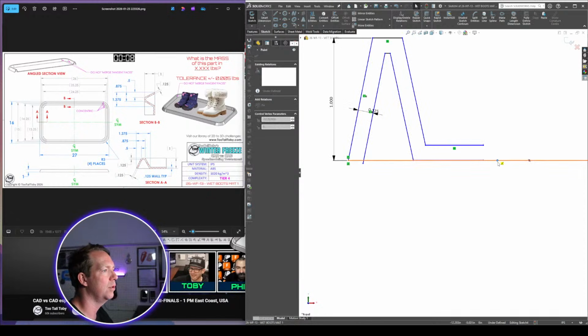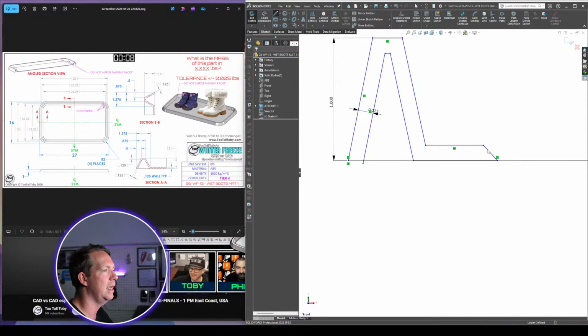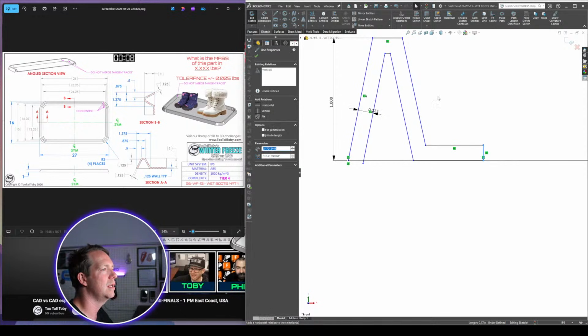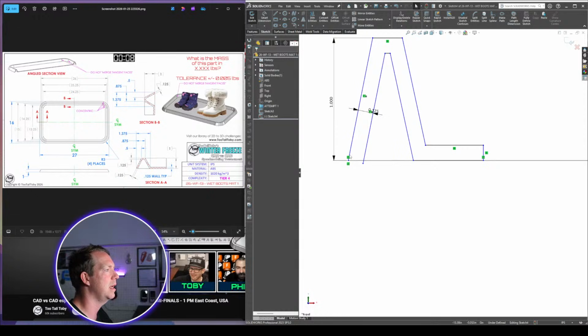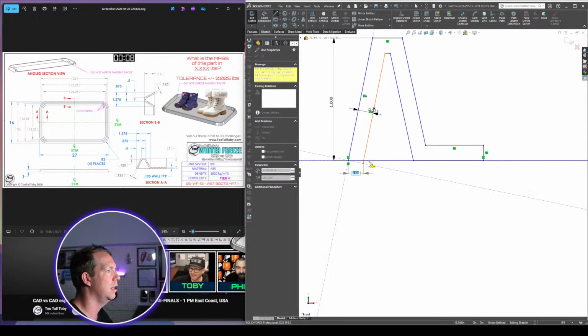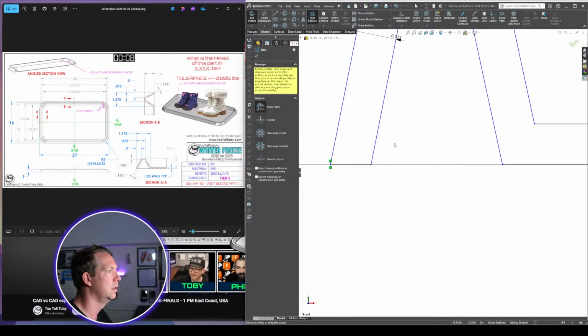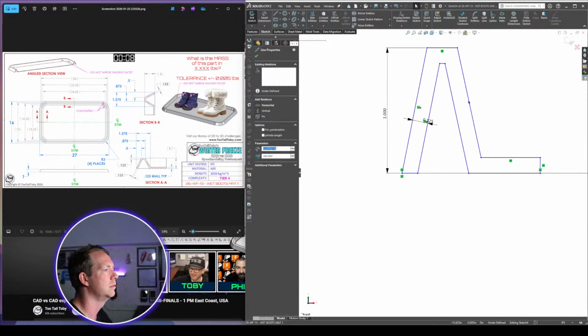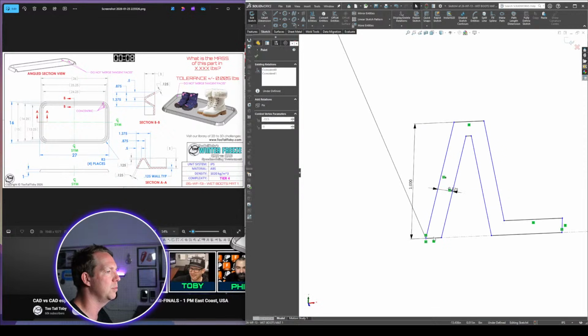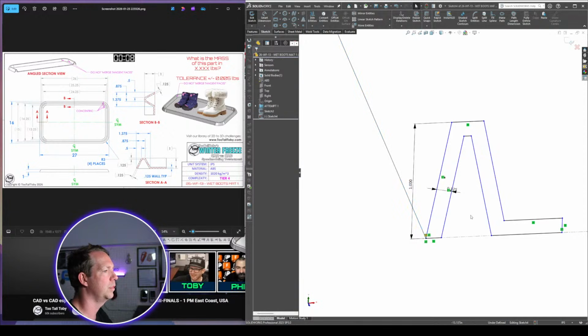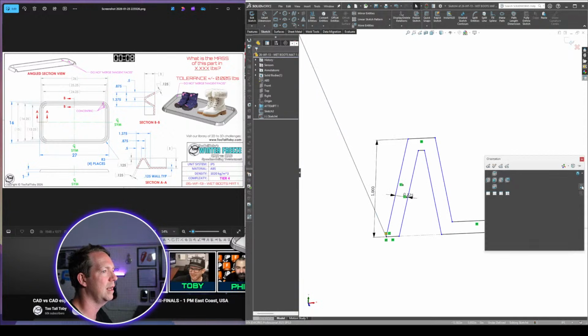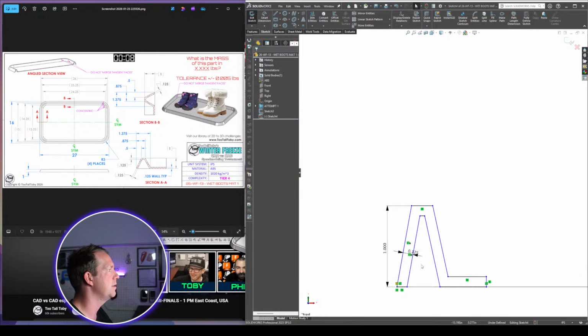All right, I'm going to bring this line down, sketch in one here on the end. This one, the position doesn't really matter, it just has to be there. And then I'm putting one here, trimming that off. I want to make sure that's horizontal. Also want to get this one to pierce. So if you can't do it by getting it coincident with the line, get it to pierce like that. And now dimensions.